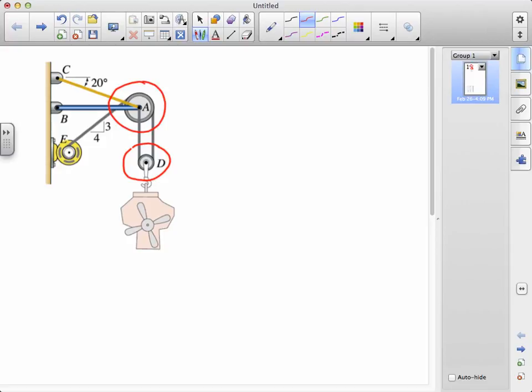The only forces that will appear in these cases will be those that are associated with cutting through different structural elements. At D, we cut through the cable ADE at two separate locations, and those are shown here. We'll label both of these TADE. We're also cutting through the hooked member that's carrying the engine, and the force that develops in that member is simply the engine weight W.